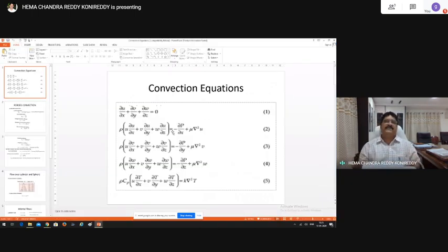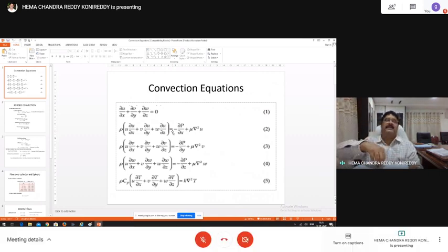Whereas for a horizontal surface, I said there may be a favorable condition, there may be an unfavorable condition. What is a favorable condition? If it is a hot horizontal surface, and air is coming in contact on top of it, it gets heated, and heated molecules can go vertically up due to buoyancy effects, and therefore this is highly conducive. Any molecule coming to the plate picks up heat from the plate, its density reduces, and it goes up. So there is absolutely no resistance to the movement, and always a colder particle can come here, acquire the heat, and go on.